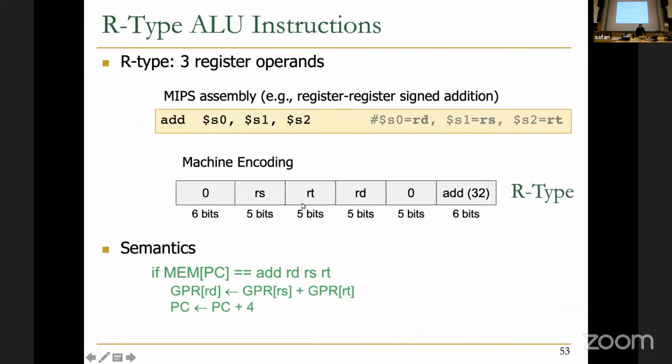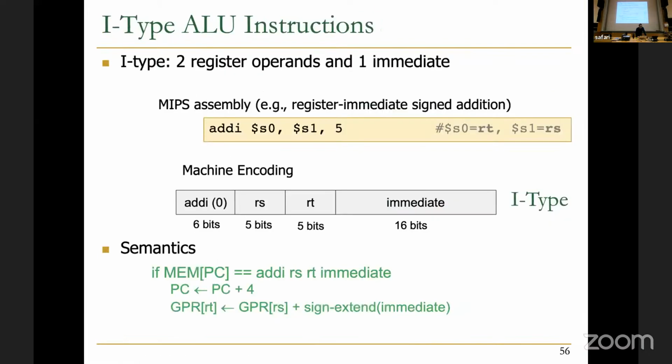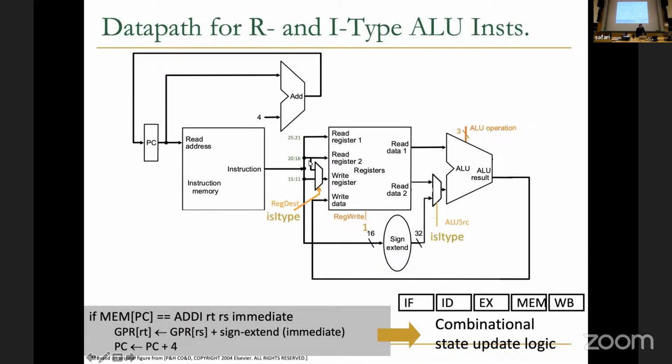Whereas if you go to the R-type instruction, the destination register was the next 5 bits, right? So you basically need to have the correct index, and the destination register in this case will be specified by bits 20 through 16, because the bottom bits 15 through 0 are the immediate, because of the specification of the instruction.